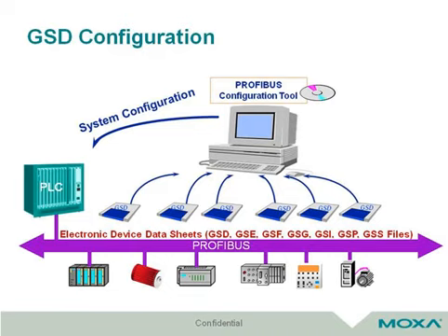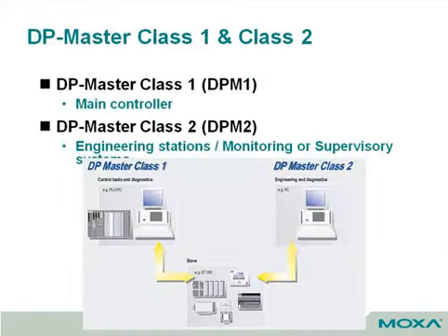In addition, there is a feature for DP version 0 communication called plug-and-play configuration. What is it? We import the GSD files of these slaves into the host. Then the host will download the system configuration into the PLC, including these GSD files. So, automatically, the PLC can operate these slaves through the features and the parameters which are defined in these GSD files.